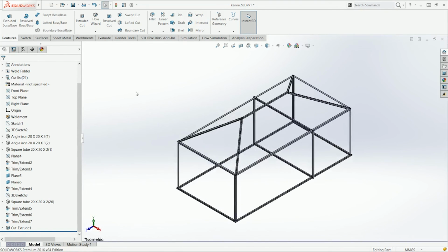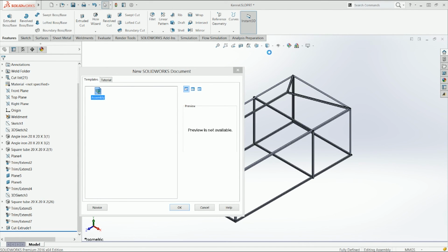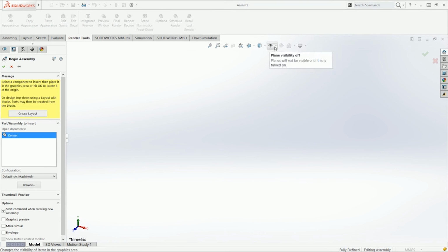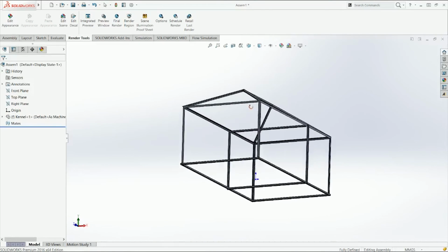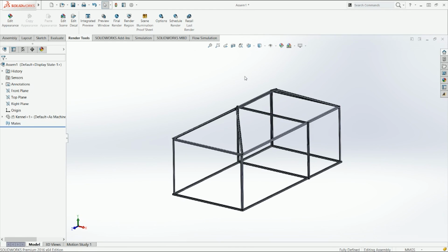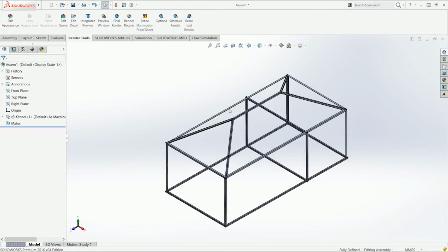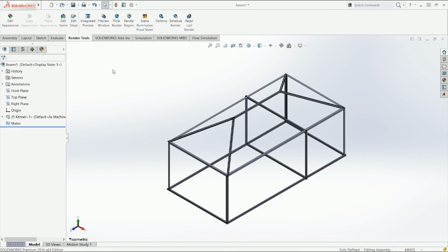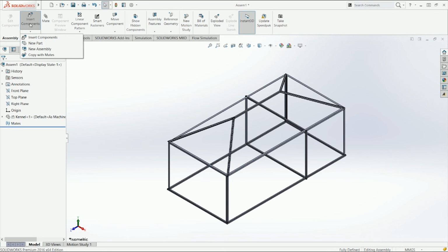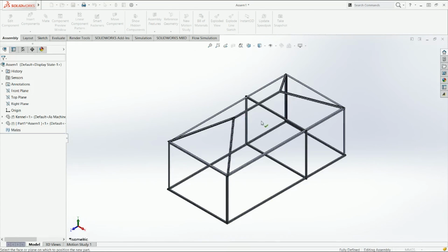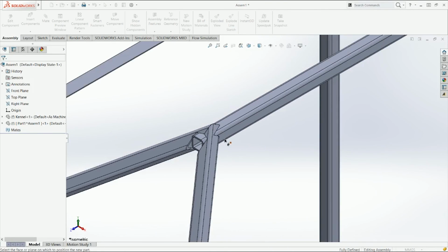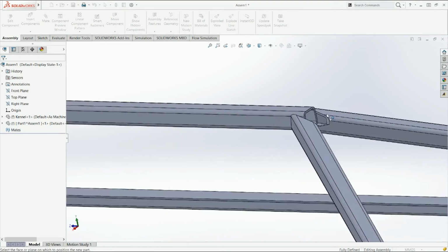So yeah, all right, I'm going to save this and I'm going to start making an assembly. I'm going to go make from assembly, then just show the origins, click on the point and the origin, so that everything is on the same side. And now I'm going to create a new part from the assembly. That's another thing that SolidWorks lets you do. You can insert a new component, but instead of clicking here, you go new part. You can now select a face as a reference.